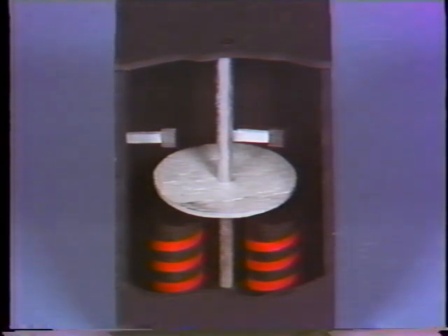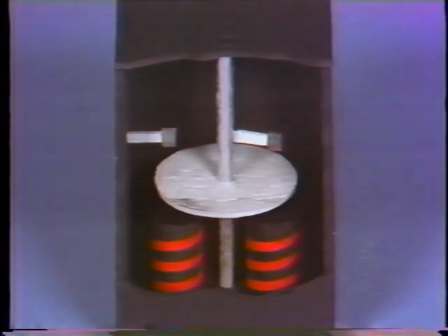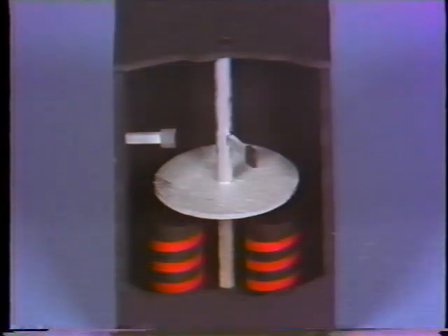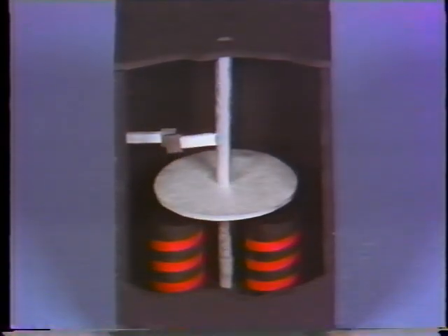The operation of this type of relay is similar to the operation of the AC induction motor that we covered in the last unit. When the coils are energized, they induce a voltage in the metal plate, causing it to turn until the two contacts touch. The turning action is normally very slow. Relays like this one are typically used as sensing relays.